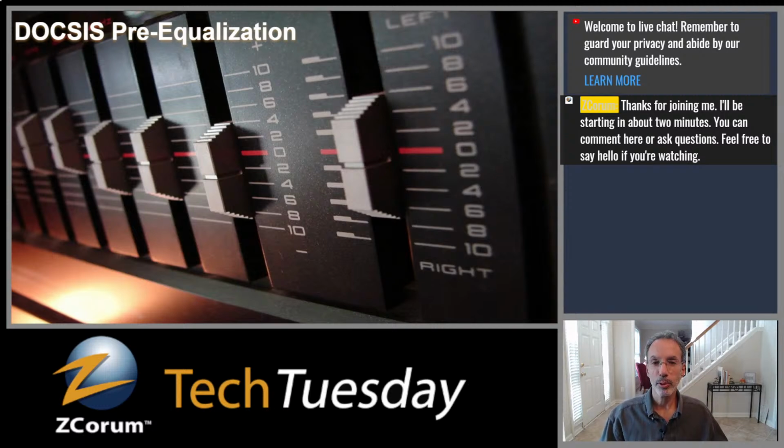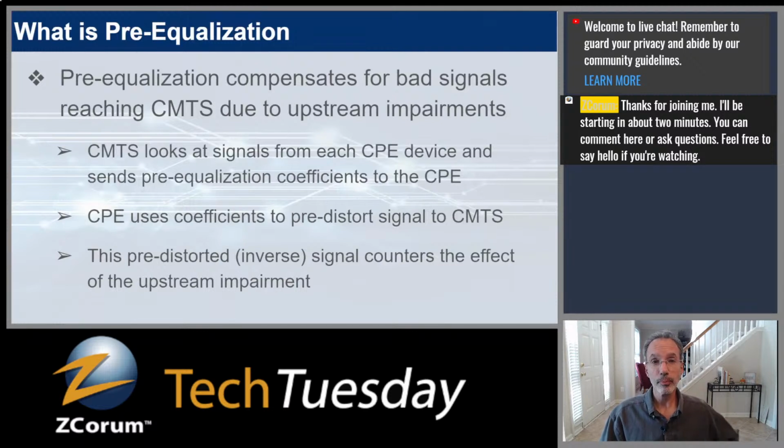Well, DOCSIS pre-equalization is very similar to that. It compensates for bad signals reaching the CMTS due to upstream impairments. What's basically happening with pre-EQ is that when the CMTS sees the signal from each cable modem, it looks at it and says, this particular signal has some tilt on it, or some ripples, or some kind of impairment impacting that signal as it comes from the cable modem to me. So it tells the cable modem to adjust its signal using equalizers within the cable modem. Really, it's telling the cable modem to pre-distort the signal in such a way that it's the inverse of what it's receiving.